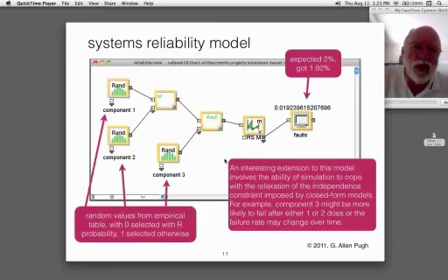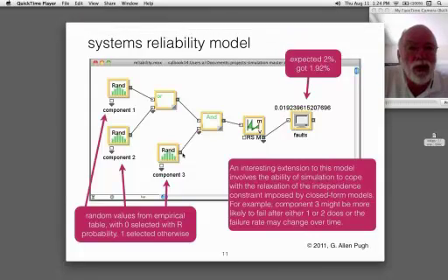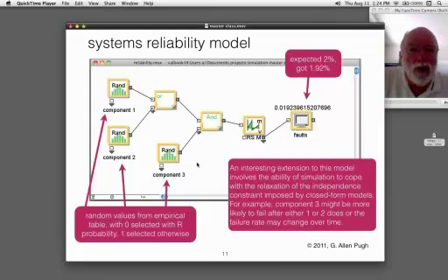And you can think of several examples. For example, if one or two fails, that means everything that's going to succeed has to pass through component 3. It may cause the failure rate of component 3 to increase. Or all the components may be in some sort of box which is subjected to external stress of some sort, such as thermal stress, which will cause their failure rates to change, and even may change those failure rates in different ways. There's also cyclical stress, low cycle fatigue, all those sorts of things that you have to consider.